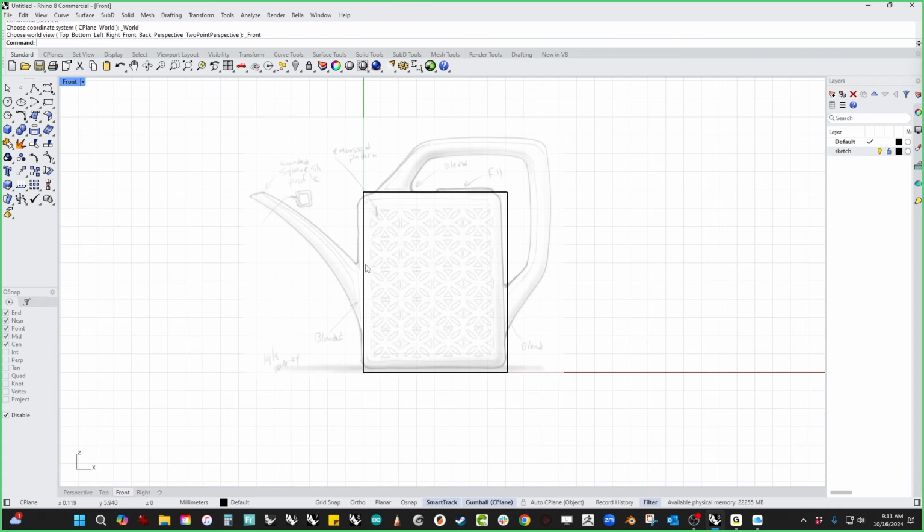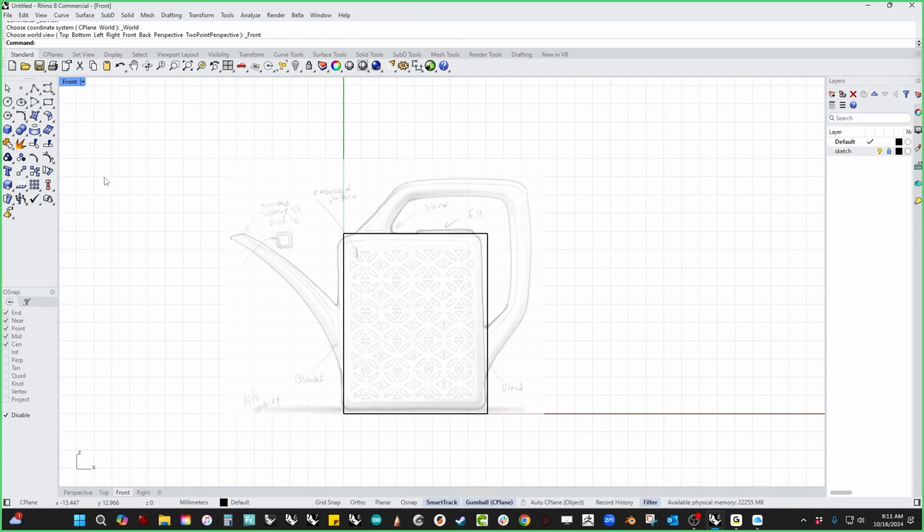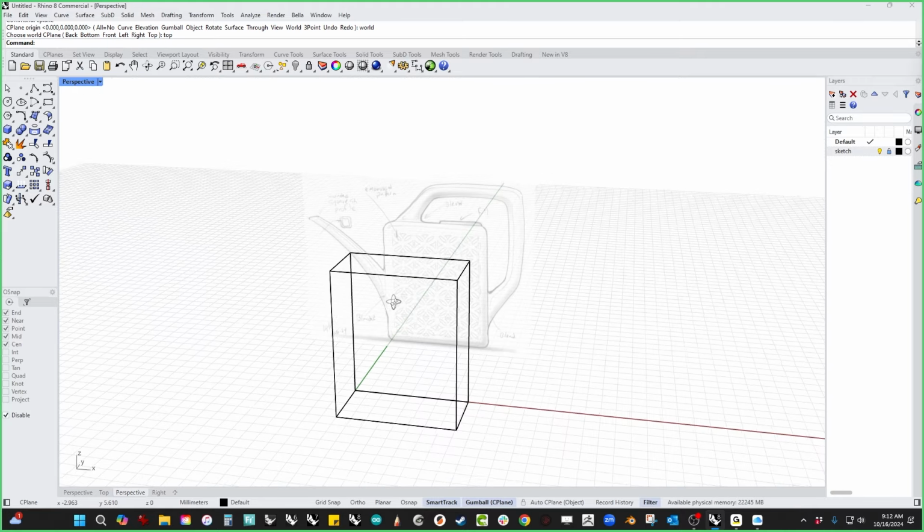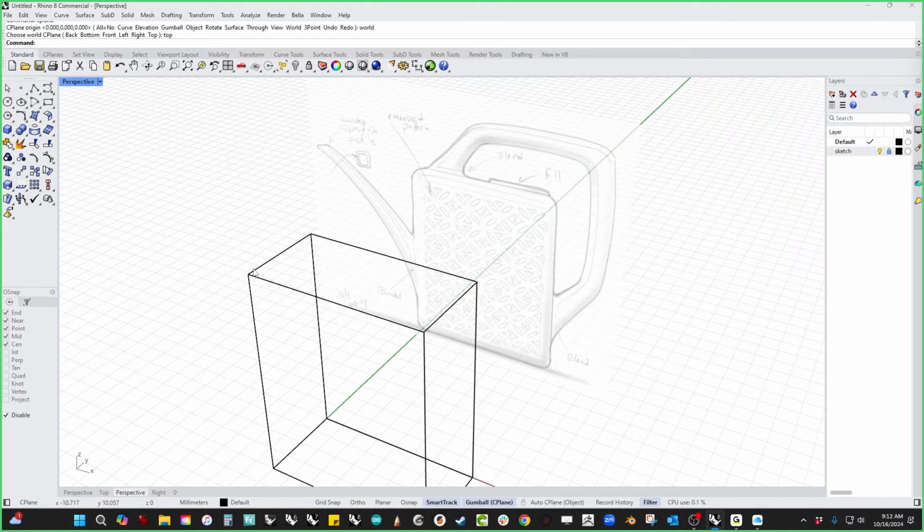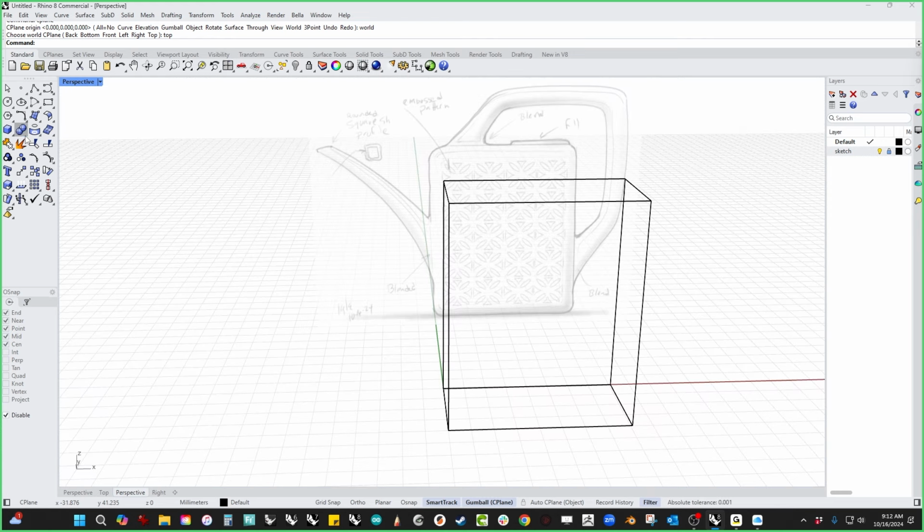The first thing I'm going to do is drop some radiuses on the edge of this thing. I'm going to fillet the edges. If we get those edges selected, actually, let's use fillet edges here. So we're just going to click all 4 of these.